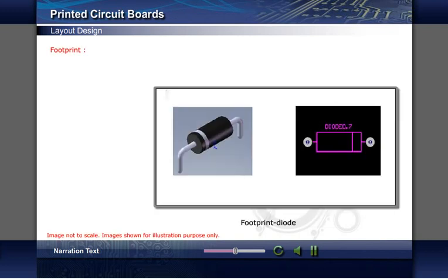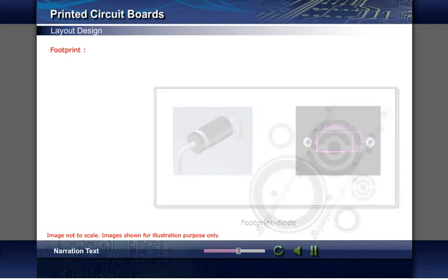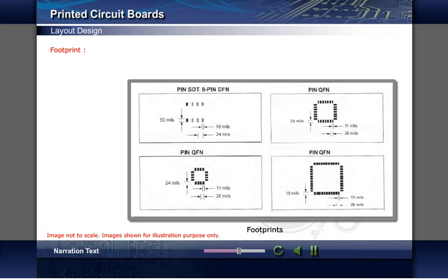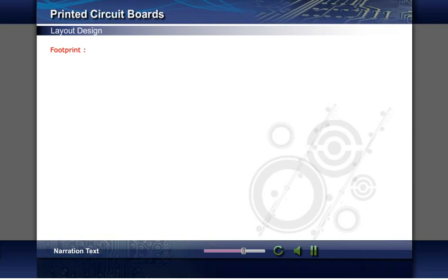Now netlist is read in software. Confirm that selected components and footprints selected by software match. A footprint is component size and its lead pattern. For incorrect footprint, check assigned footprint in circuit diagram. Else select correct footprint from library. Else create footprint referring to component datasheet and add to library.